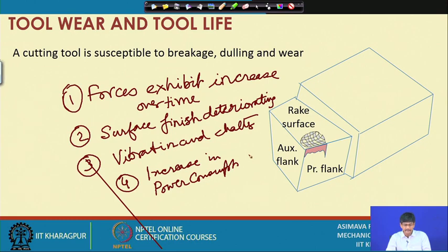There can be too much heat coming out from the color of the chips, etc. It can be found out. So, lots of indicators will be there showing that the tool has reached a particular amount of wear.